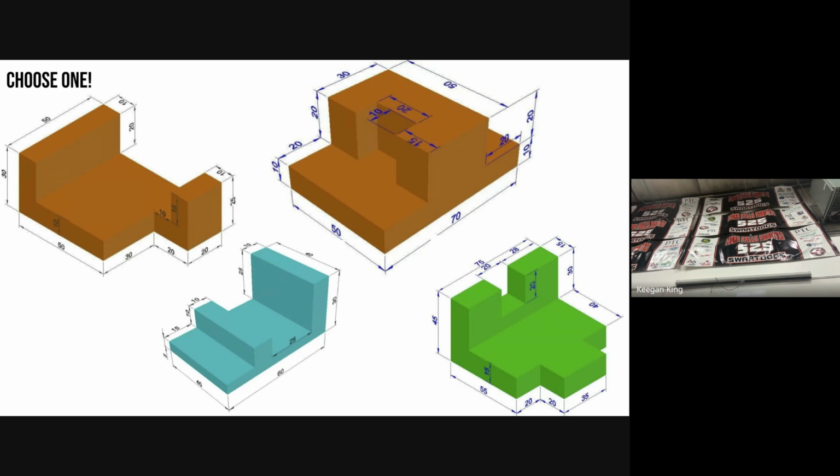Just put it on first. Add or not, it's people's preferences. There are a whole bunch of different ways to do it. I've done designs where I've linked them all out of one base sketch and then extruded them all separately, because the dimension I want is from the bottom to the top, and I don't want to do the adding because then I trip myself up.